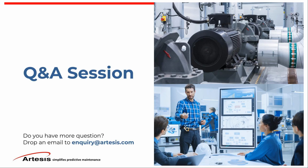Another question here is on the stator wedges loosening. We are not able to say that this is a stator wedge issue. However, we can say that it is a stator problem. So you may need to follow up with other tools to dive deeper on that stator issue. This will give you the first indication that your stator has issues. So I think this is how you should look at this technology.